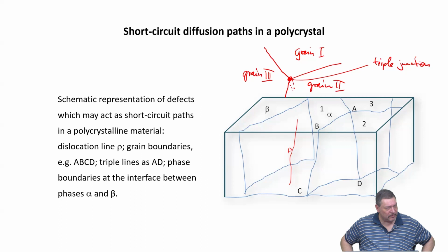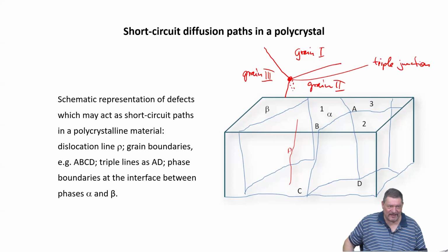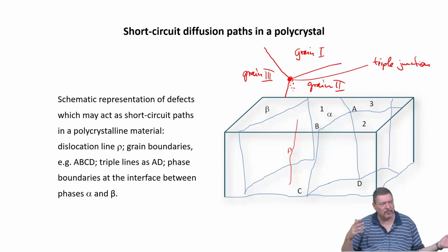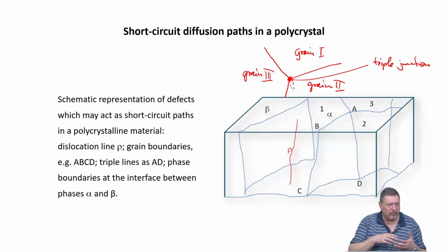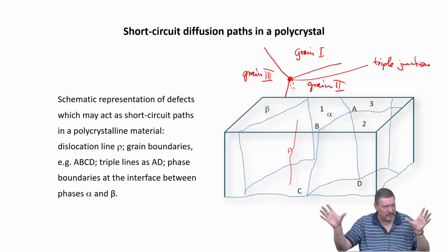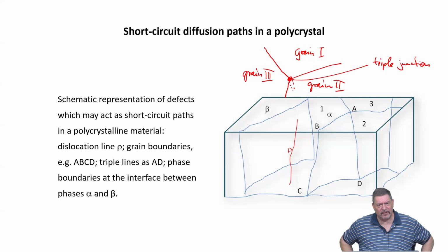It might be. In the literature, actually, there have been reports going from much less energy, specific line energy of the triple junction as compared to a dislocation. There have been reports on the opposite, that it's more. It's a huge discussion over many, many decades. When you normalize this specific line energy with something like a grain boundary energy, always for the unit length or the unit area, so that you get just an energy, then people have termed this as either positive or negative triple junction excess energy.